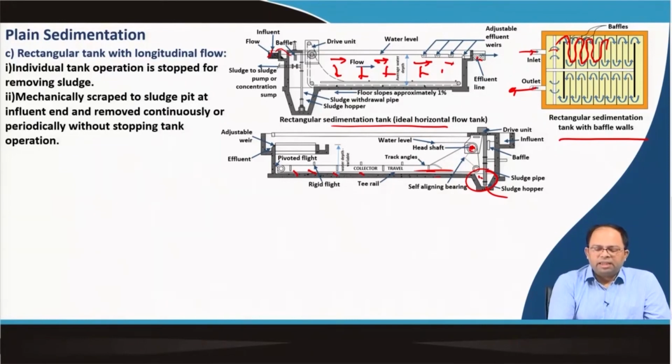So, in the first design, the sludge was taken back to the point where the influent is put in. One benefit of this is that heavier particles do not need to travel far when the influent comes in, because some of the very heavy particles immediately settle and come to this particular sludge pit. But the other design is where the water enters over here,